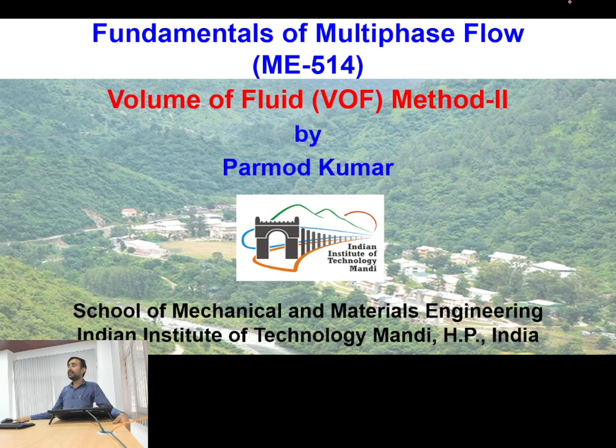Then next point, I already told you that when we do the volume of fluid method computationally, we have to discretize our governing equations. Our governing equations are continuity, momentum and volume fraction equation. Discretization of the volume fraction equation I have already shown to you, and regarding the discretization of continuity and momentum equations, particularly for Newtonian fluid, which are called Navier-Stokes equations, I have given you the reference of 5 lectures of CFD from where you can learn that.